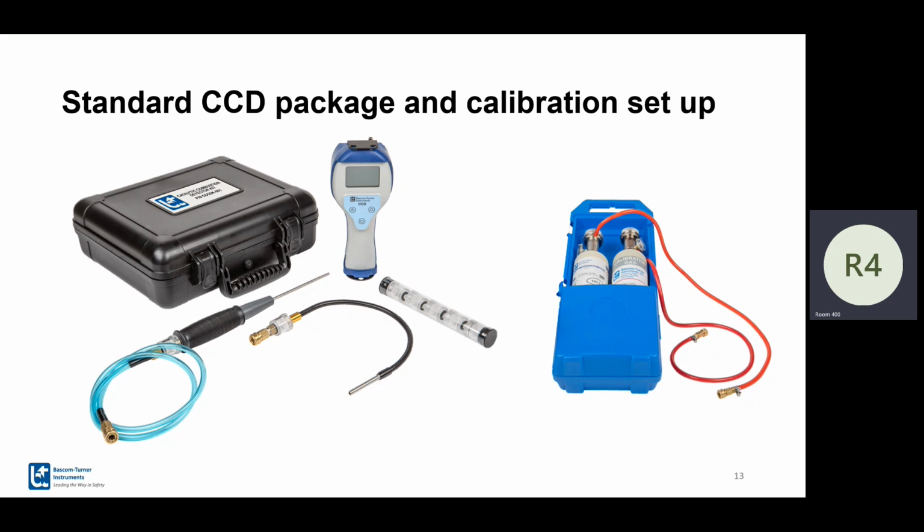With the amount that this user group calibrates, given multiple calibrations a day, sensor drift should be very minimal. When sensor drift would happen is typically with low battery life. You're just not getting enough pump into the sensor, but you're going to see it on the machine. So if you keep your batteries charged and your filters clean, drift is going to be very, very minimal. What gases? How long does one cylinder like that size last you?